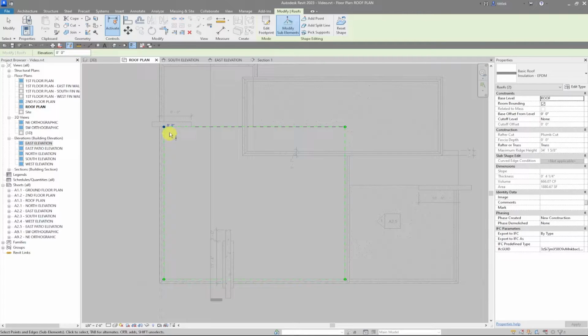You can select those and you'll see that they have an elevation of 0. So 0 is essentially the top of my roof, or the top of my EPDM surface. So 0 is essentially what I want to drain to. So I need to raise this up to 5.75 inches. And I'm going to do that for all of these. And unfortunately, I can't do multiples. I have to do them one at a time.